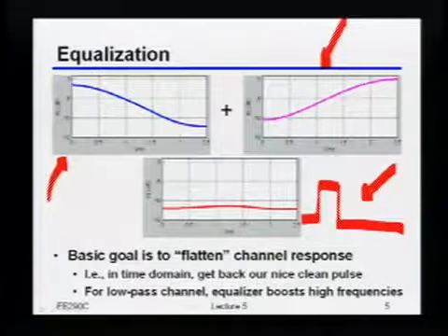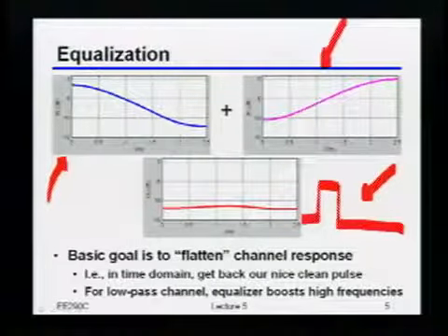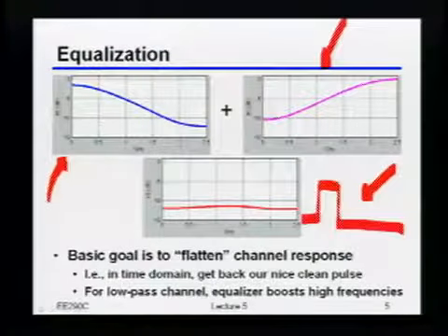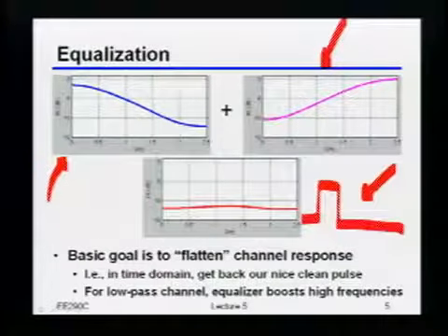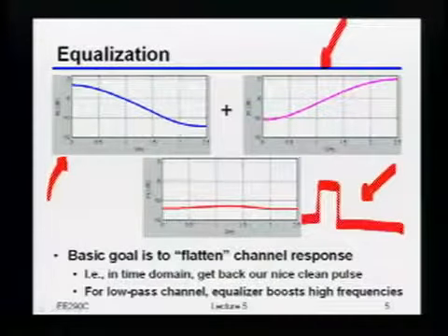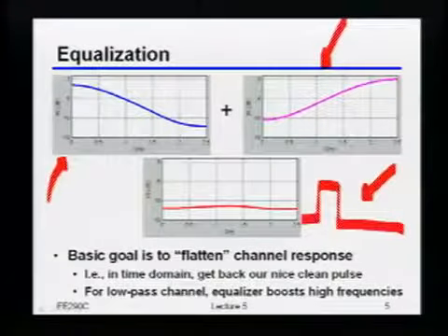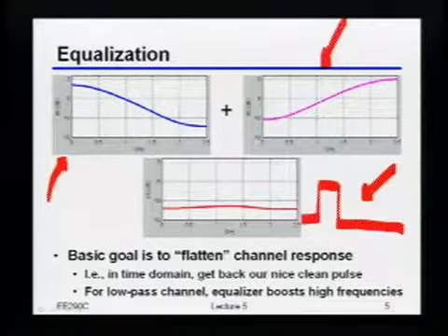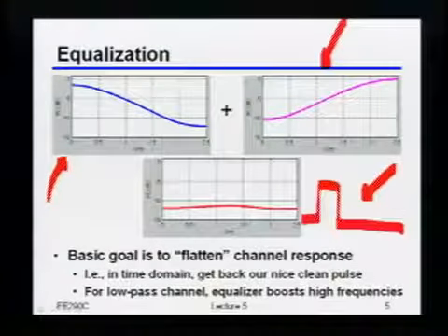There are maybe some caveats to that if you look at the ESD, where the capacitance of the ESD maybe gets modulated. But as long as your signals are reasonable, that doesn't have too big of an effect on what I'm saying here. If it is nonlinear, of course, you could deal with it. But generally speaking, I haven't run into any links where I really had to worry about that yet. It's a good question. Actually, I'll take that back slightly.